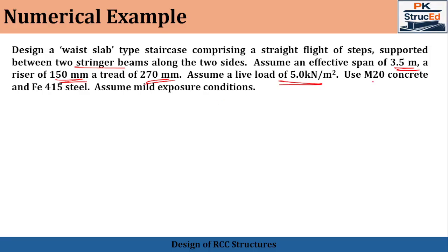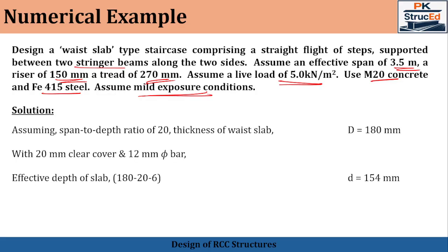Here the materials used are M20 grade concrete and Fe 415 grade steel, and the staircase is to be designed for mild exposure condition. So this problem is very typical of staircases used in public or commercial buildings. As with slabs, staircases are governed by deflection control.